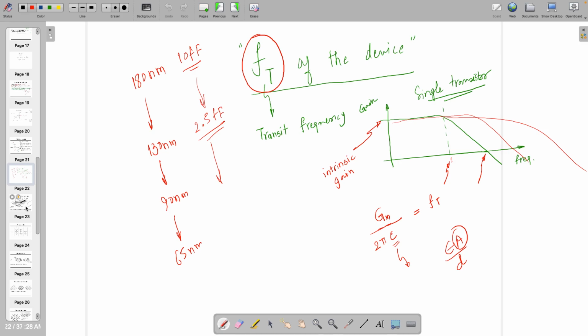In 180 nanometer technology, as you're going down, of course, you can try even for terahertz, and people are doing it. All the communication people, right? So depending on the FT of the device, you can determine it. The thumb rule might be to divide by 100, and it should work. I'm talking about the bandwidth. Gain, as much as you want, you can achieve, no problem. 100 dB, 200 dB, no problem. There are some techniques through which you can achieve it.